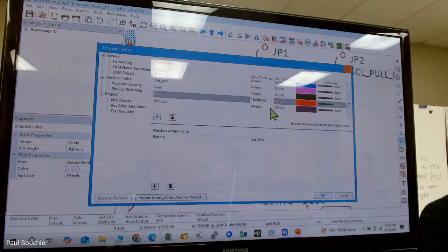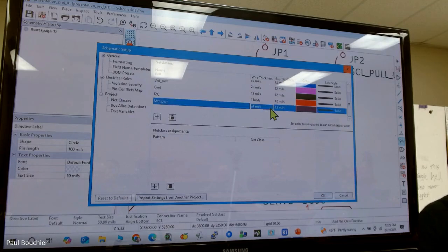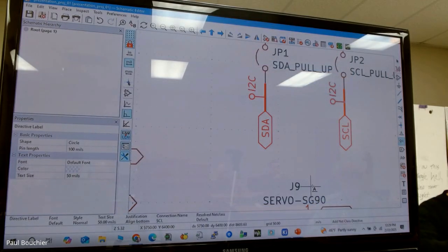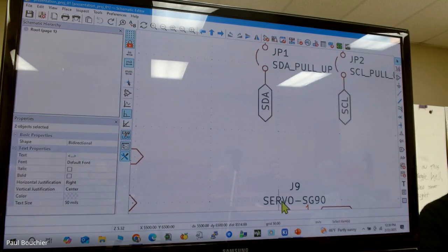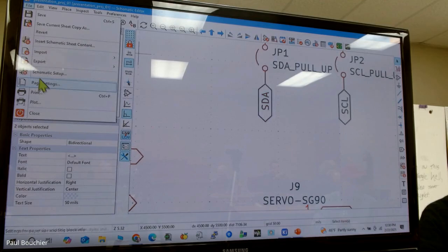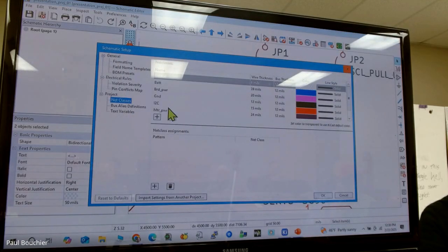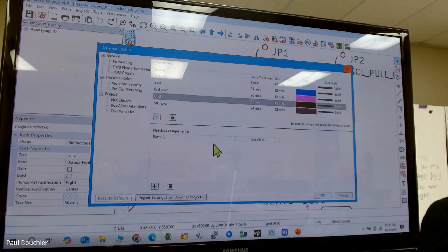Right now, I don't know why, because I thought it defaulted to millimeters, but here you can see the bright red lines, thick lines. So that's how you do it. Now I'm going to do control Z out of that and check to make sure I got rid of it. There's no reason why you couldn't leave it there if you wanted to. The nice thing they've done in 7 and 8 is that both in the schematic and in the PCB editors, the classes are synchronized. It used to be that it wasn't synchronized, and that got to be a little iffy.